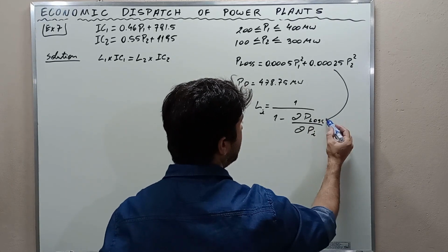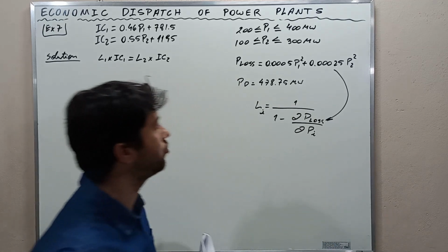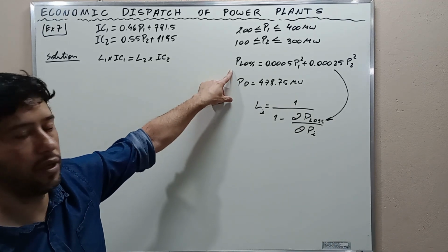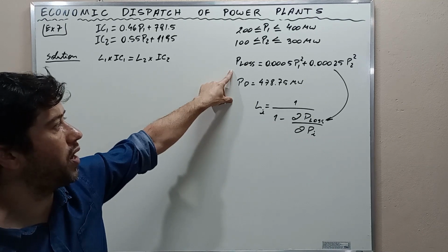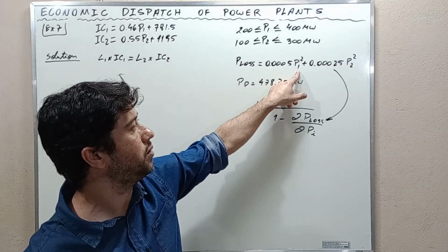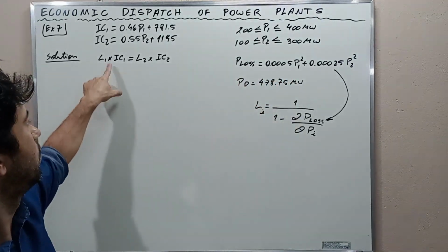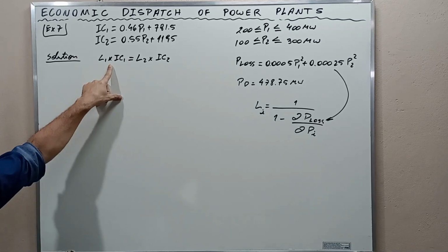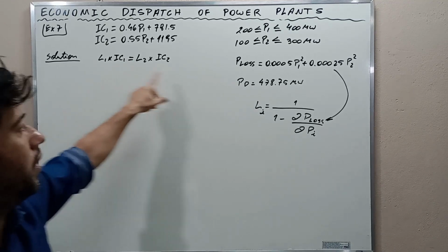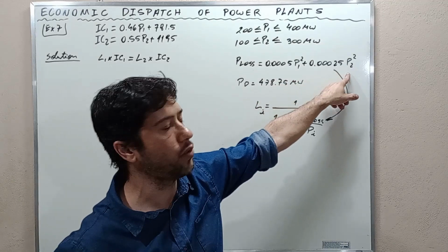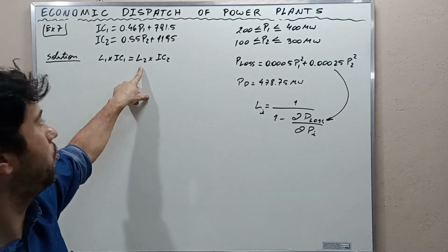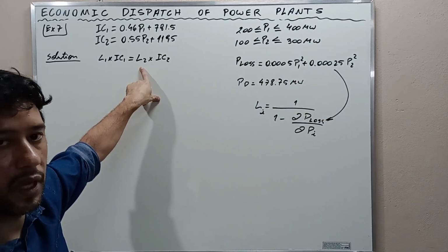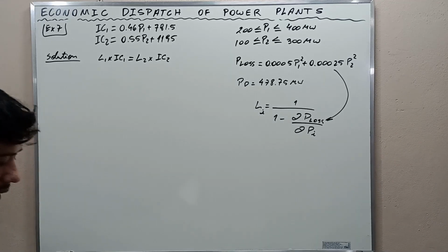We are going to differentiate this expression with respect to P1 to calculate the penalty factor L1, and we are going to differentiate it with respect to P2 to calculate the penalty factor L2. Okay?